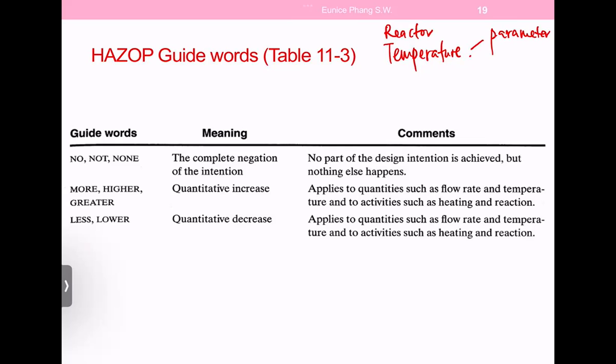So when we have temperature, what does it mean when there's no temperature? Does it work? If there is no temperature, that doesn't make sense, because no matter what, we always have a temperature there. When there is no temperature, it only shows one thing: our controller, our temperature sensor or our display is faulty.